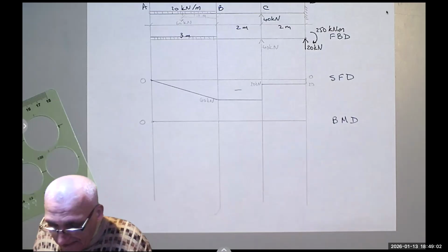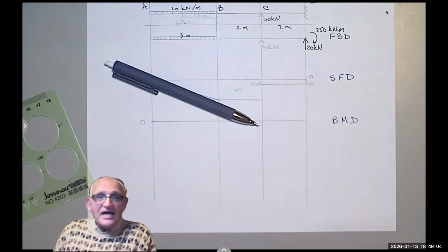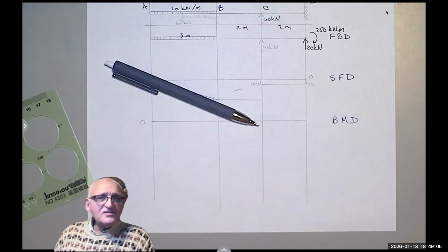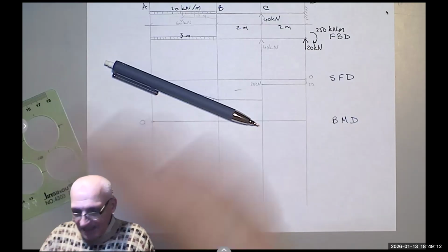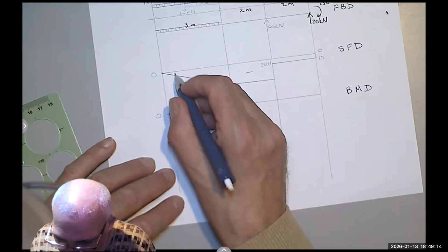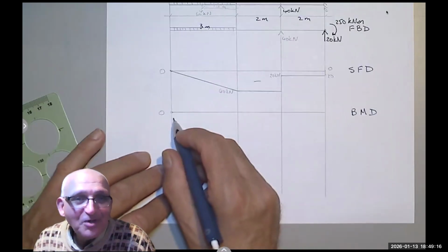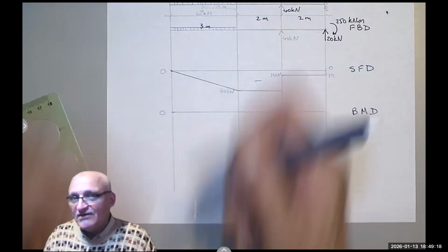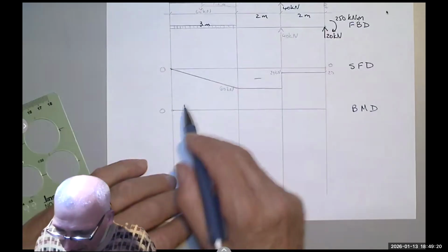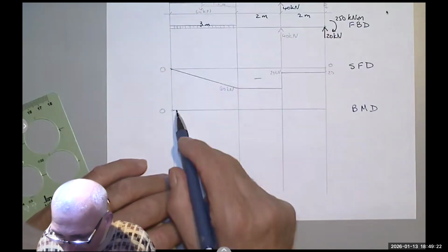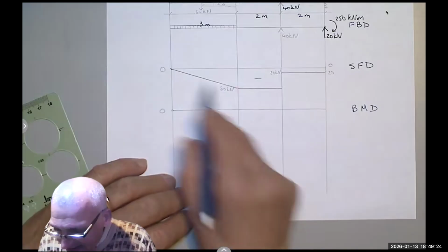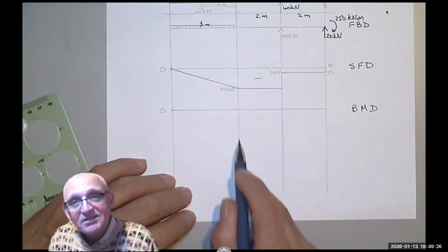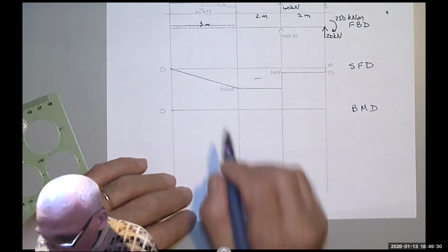Well, that's a straight line, meaning a first degree curve. When I integrate it, it will become a second degree curve. Notice here, this is the slope of the bending moment diagram, because that's the derivative of the bending moment. So the slope is small, meaning I'm close to the 0, and then it gets larger. It's turning like that. Do you see? So now,